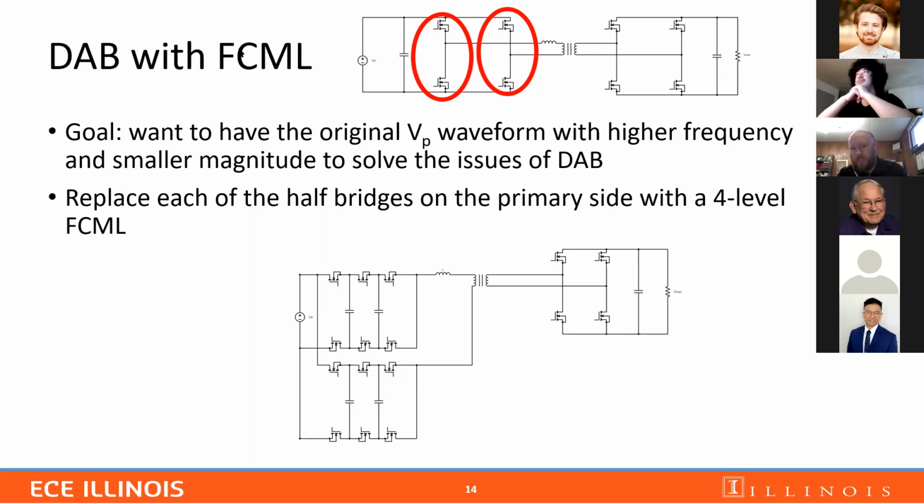We're at a higher frequency, which has some benefits. The voltage level is lower, so our tolerances and our spacing are a little bit better. But those are really fundamentally it. We state that there are some benefits to the transformer in terms of size, but they are not as dramatic as what we've seen for the inductor and the FCML in the past, for example. I see. Okay, yeah, because it's not the n squared we've seen in the past. They're at most linear, as opposed to a squared type of situation.